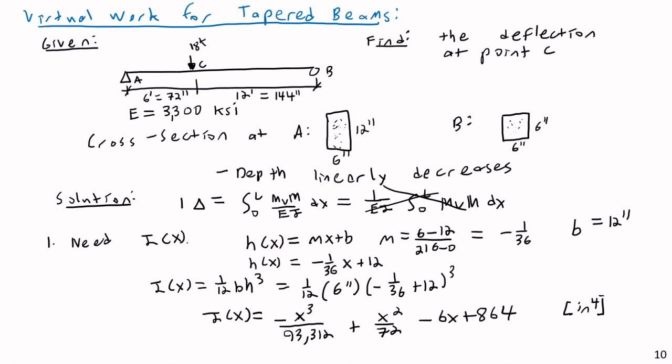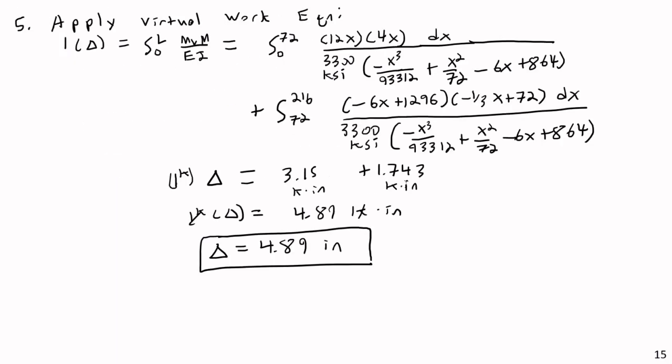So you'd end up with a much reduced deflection if you used a continuous 6-inch by 12-inch beam, and I don't want to think of what it would take to actually fabricate a tapered concrete beam like that, but it would not be fun. So let's not worry about such things. But there are cases where, as structural engineers, you may need to calculate the deflection or the behavior of a tapered beam. For this particular problem, the deflection ended up being quite large. For a beam of that span, that would probably not be a satisfactory or allowable deflection, so you'd have to go back and redesign the beam. For example, the easiest way to redesign it would be, let's just get rid of the stupid taper.